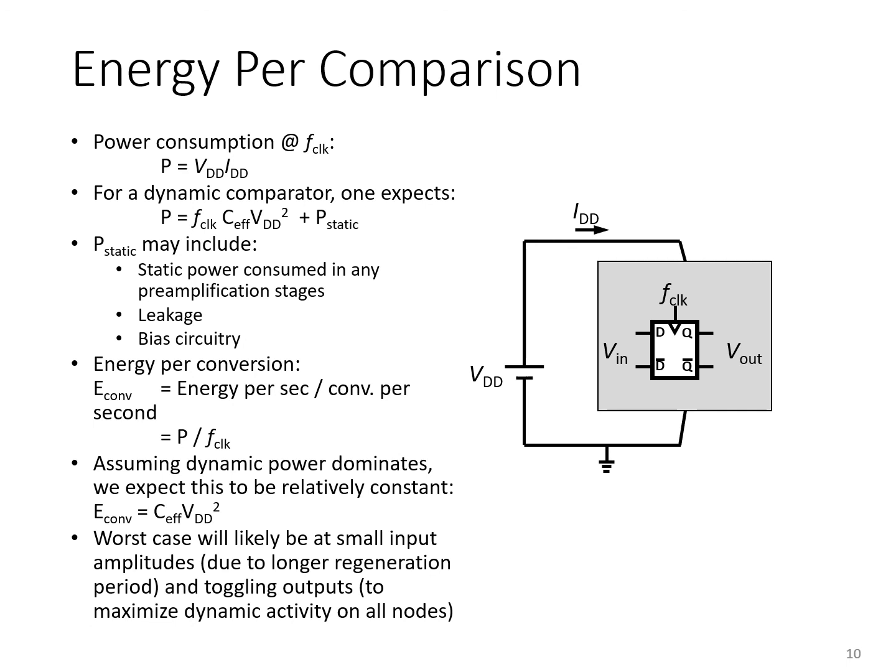You have a DC power supply supplying a current IDD to the comparator, and you clock it repeatedly. What you can expect to see if you look at the current waveform here is obviously not going to be a steady DC current. There'll be periods of time where there's probably little or no current flowing in a dynamic comparator. There may be some finite current always flowing if, for example, you have a simple resistively loaded differential pair as the preamplifier. But there will certainly be spikes of current that arise when the regenerative comparator is activating, for example.